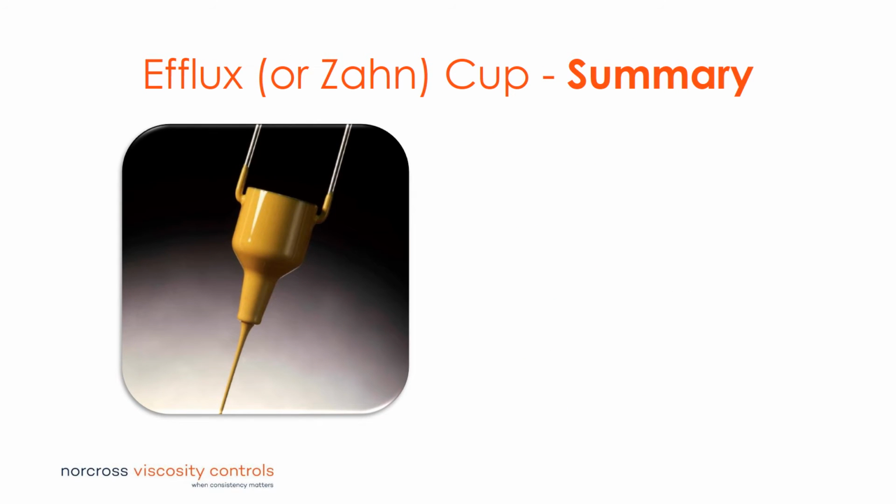So in summary, pick the right cup. Start by understanding the range of viscosities you will be measuring, then use our online viscosity conversion table and make sure you get the right cup for your fluid. They're inexpensive, quick, easy to use, and they're the benchmark in the industry. You will find that you use it frequently, even if you only use it for spot checking during runs when you're concerned that something may be off.